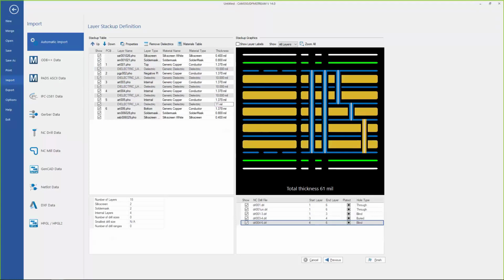And why that's important is that I can actually, and you won't see it in this menu, but in the Stackup visualizer itself, I can actually export this as an applet. And I say an applet because what it is, is a reduced version of the IPC 2581 specification, which just has the Stackup information. And then I can bring that into another tool. And in this case, I'm doing it in CAM350.